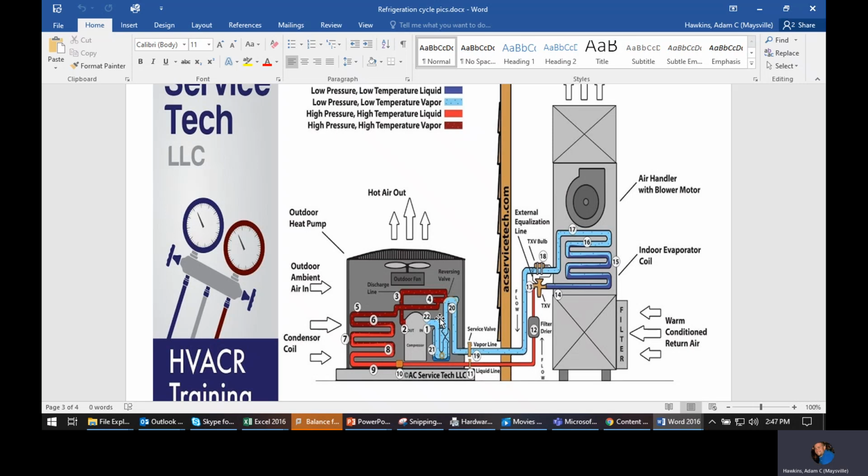Well, now what was supposed to work one way is working a different way, because it was designed to have X amount of air, and now you've slowed it down or cut it off. So airflow will make my pressures drop on my suction side. On my head side, it'll make my pressures go up, right? Because what are they doing?